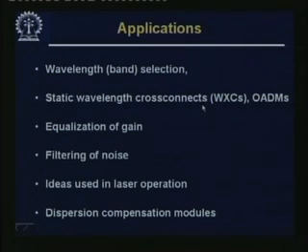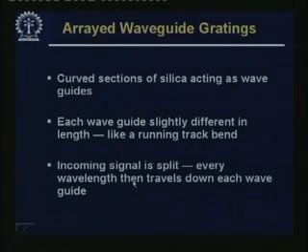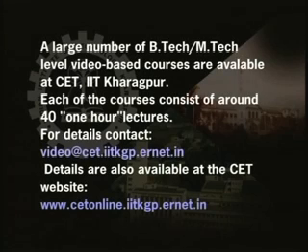Static wavelength cross connects and OADMs. The OADMs are optical add drop multiplexers. We have come across the term add drop multiplexers in the context of SONET, but in the optical domain we require optical add drop multiplexers. We will come to that. Equalization of gain is another application. Filtering of noise, ideas used in laser operation, and dispersion compensation modules, etc. These are the different applications. One of the standard wavelength selective components is the arrayed waveguide grating. We have seen this before.